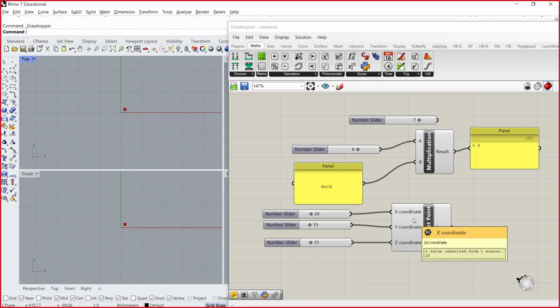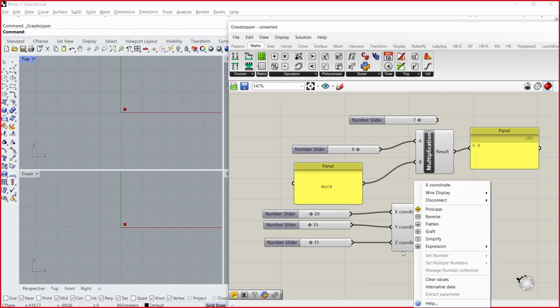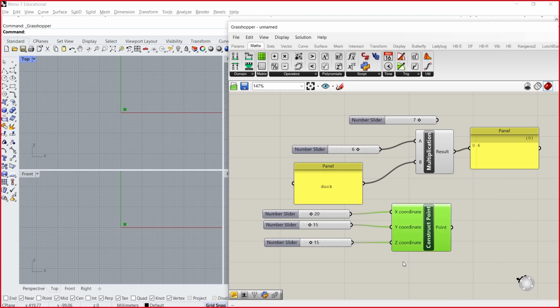Okay? So because it's red, it indicates that it's geometry that we have in Rhino. So if you click on the node, it'll turn green. Okay? Yeah? So this is how we know which nodes are responsible for which geometry. If I click on this, it turns green, which means I've selected this point, and the representation of it is in Rhino. Yeah? And then you can move this around, and you can see the point starts moving, right? So what we're doing is we're controlling the position of the points based on the 3 values. Okay?